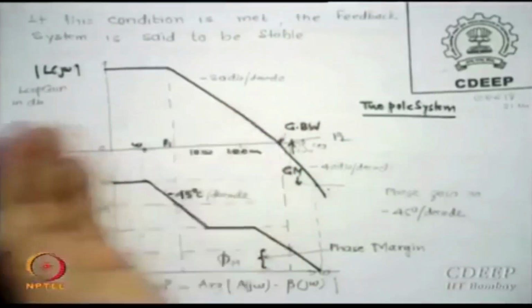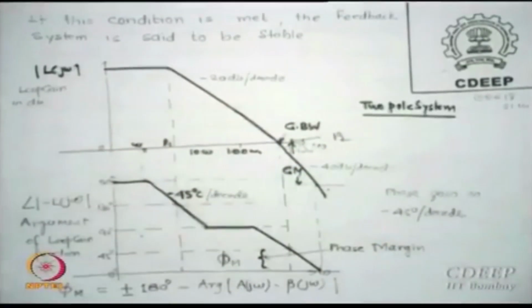If the pole is one decade ahead earlier, then you are actually hitting 180 degrees, and any problem starts in parasitics. In the circuits we believe that we have assumed all the parasitics properly, but there are metal lines in the actual chip, there are poly lines, there are metal oxide metal lines. At some nodes they may contribute to some parasitics, and each capacitance will give another pole, and let us say it happens to be earlier than this, then your stability criteria is in haywire.